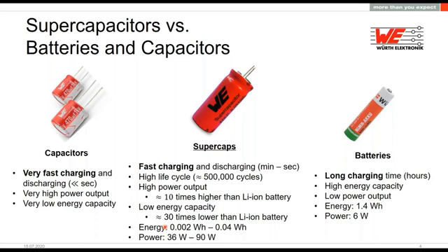Also compared to traditional capacitors, it's quite the same. But of course, the power output compared to a normal capacitor is much bigger. But also, comparing the rated voltage, traditional capacitors are higher. And again, batteries have higher energy density and of course also a constant voltage, but have a low power output and a relatively low cycle life.